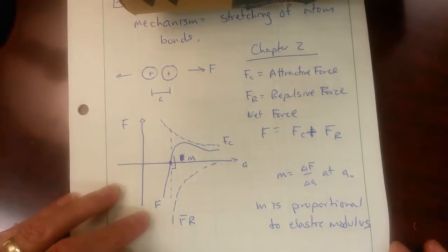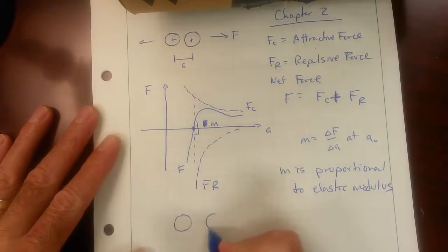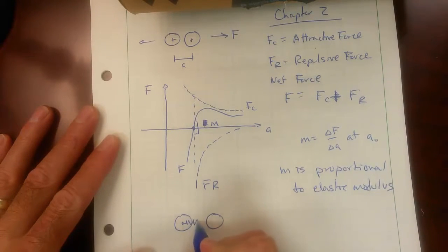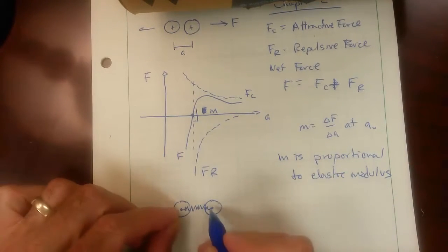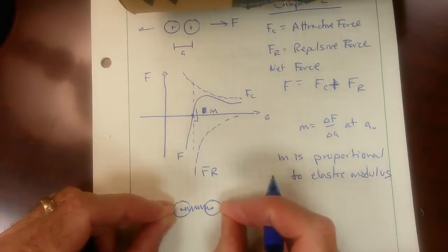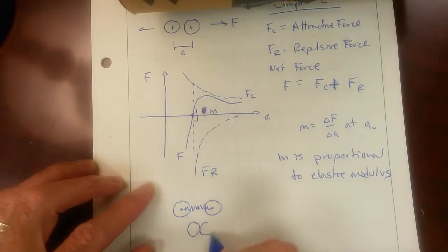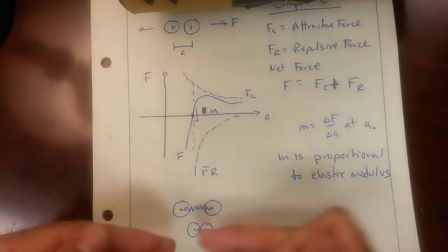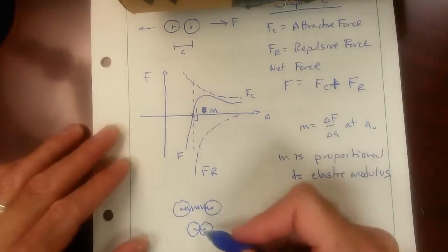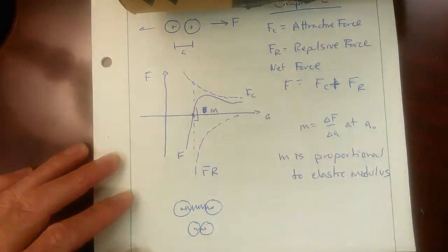So that's pretty simple. You can almost think of the elastic deformation acting like a spring between two spheres, where if we pull them apart, the spring wants to pull them back together. As we compress the spring, the resistance increases until we get to a point where the two spheres are actually touching, at which case the force becomes infinitely large to move them any closer together, which is why this curve drops sort of asymptotically.